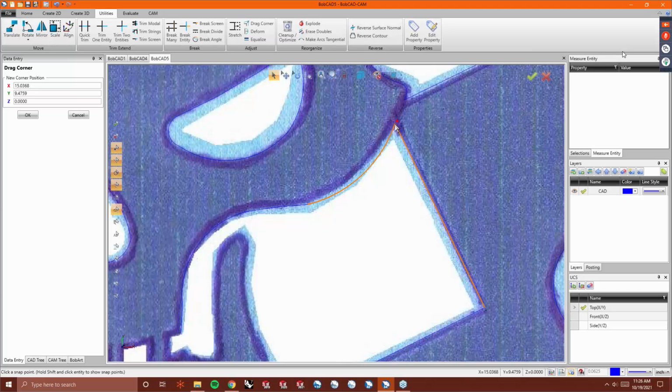You would want to resize after you vectorize. So Kenneth is asking, so you need to resize before you vectorize. Now you would want to, if you're scaling this up, you would want to get all of your vectorization or tracing everything and then resize it. Because if you resize it ahead of time, it may not give you the size that you think.